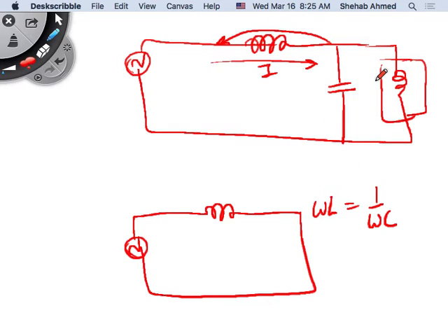But of course there's no load that is only a pure inductor. There's a resistive component. But basically what happens is now I do not need this reactive power to come, because, let's say this is an RL circuit, this looks like a pure resistor in this case. I do not need to supply any reactive power to this anymore. I just need to supply the real power that it was consuming. Right?